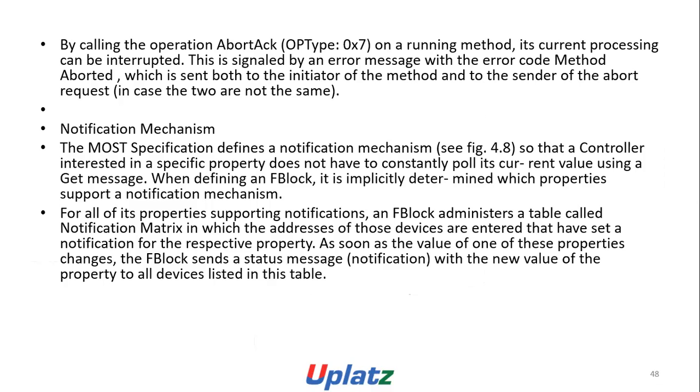Notification mechanism. The MOST specification defines a notification mechanism so that a controller interested in a specific property does not have to constantly poll its current value using a get message. When defining a block, it is implicitly determined which properties support a notification mechanism, or all of its properties support notifications.